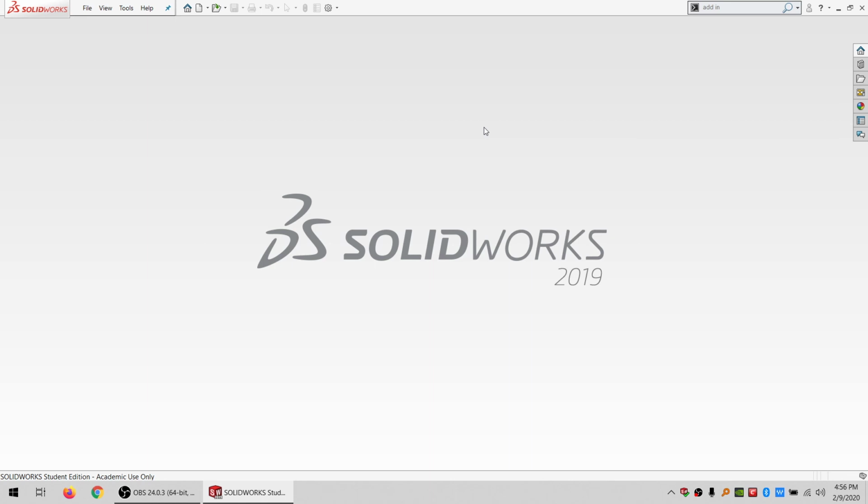since I do a lot of stuff for laser cutting, which is wood, it's interconnected and interrelated, and assemblies in SolidWorks just really don't like it when you've got a bunch of different parts referencing each other and driving each other, and feature one in part one drives feature two in part two, and then feature two in part two drives feature three back in part one again. It's not a fan of that at all. Whereas you can get away with it if you just use multiple bodies. So yeah, I usually end up working almost entirely in parts just because I use a lot of wood. But at some point, I'll definitely probably be designing something more mechanical that I can make good use of the assembly with. So that's all I've got for now.